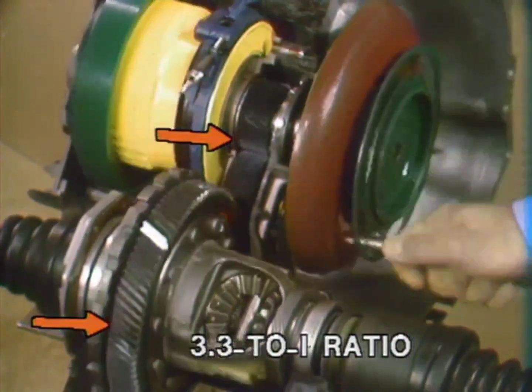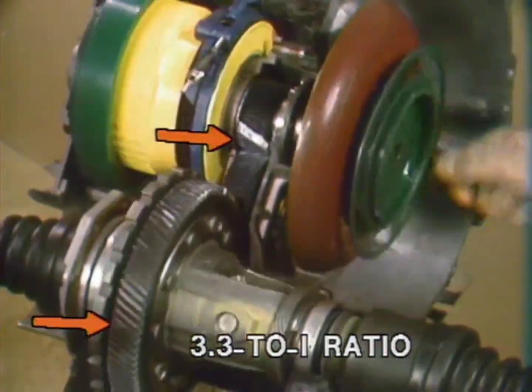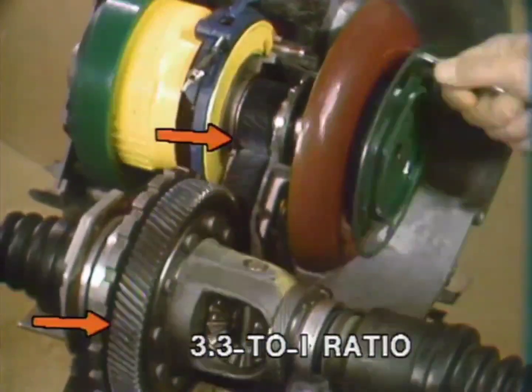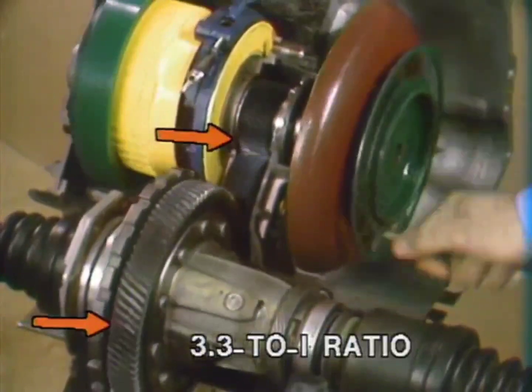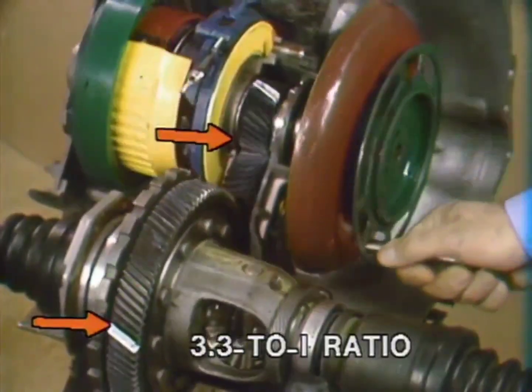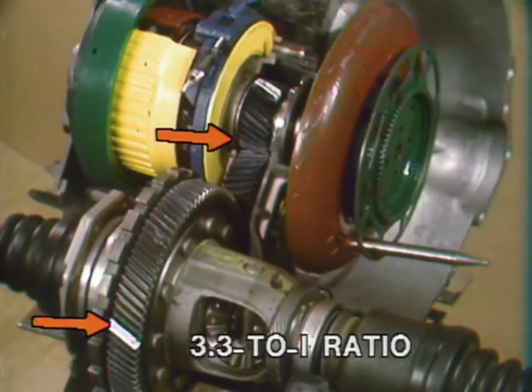Count the turns of the input gear. 1, 2, 3, and 1/3 to 1 revolution of the final drive output gear. The final drive has a 3.3 to 1 ratio.